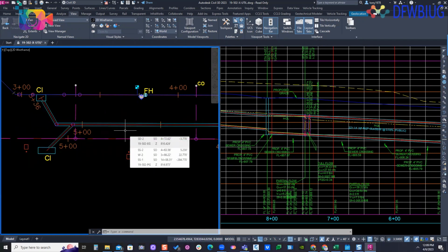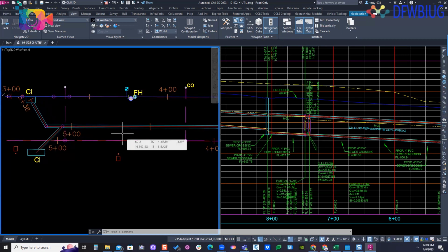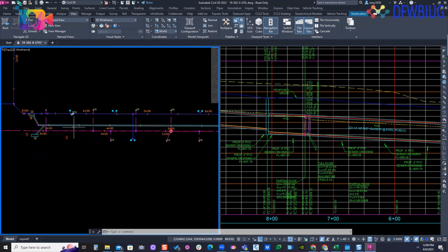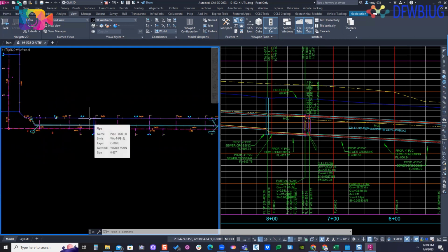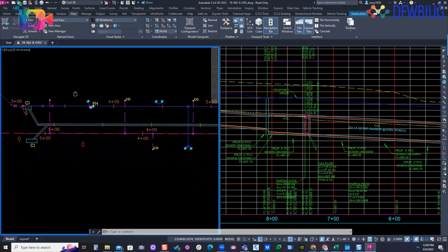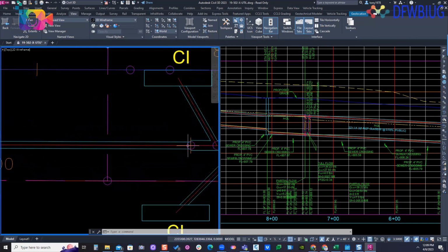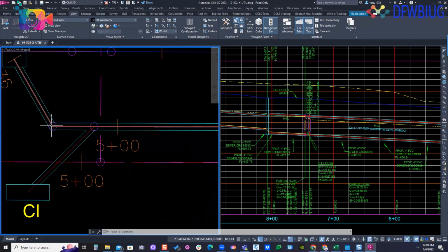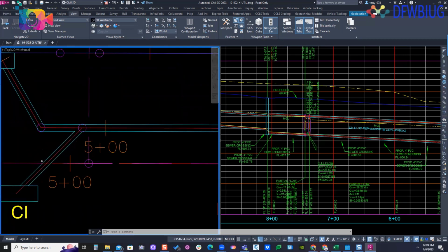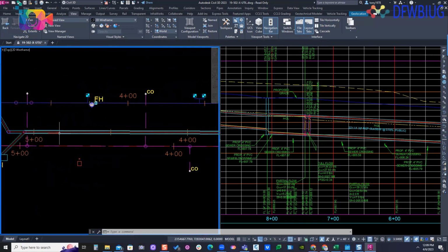If you've got a more advanced spreadsheet, I have my own personal one I've used for many years, and I keep tweaking it. It calculates a lot of stuff for me, even hydraulics and velocity flow. But there are also limitations, because the spreadsheet can't calculate when the water goes from partial flow into full flow conditions. If you have a long pipe run, from this connection here, and a pipe size change right here up to this horizontal bend, or this Y where this lateral comes in, the spreadsheet won't know when that turns into a full flow condition pipe.